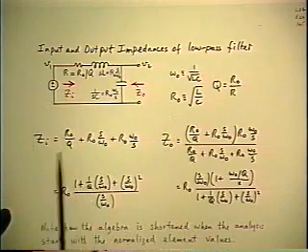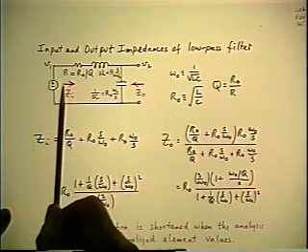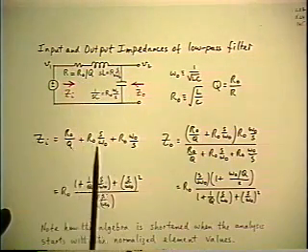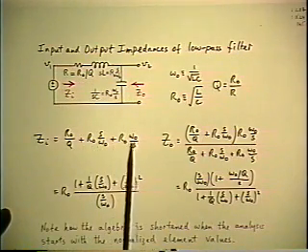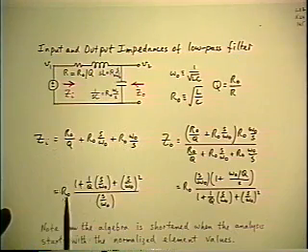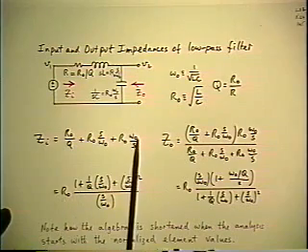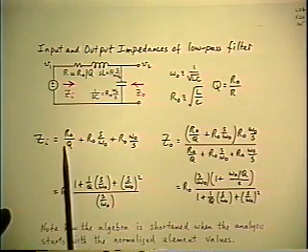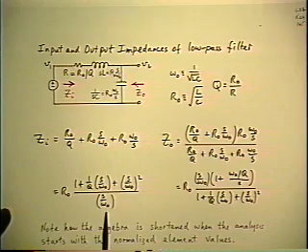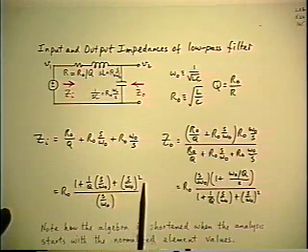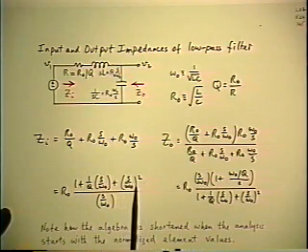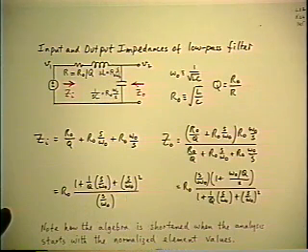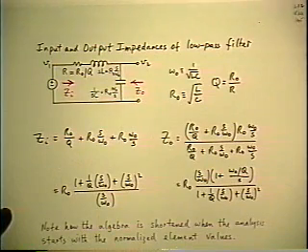So that now, in the very first line, when you write the input impedance, you simply write down the sum of those three reactances, and immediately you see that the R0 is a common factor. And in one more line, by bringing the omega 0 over s out front and putting it in the denominator, immediately you reconstitute the same quadratic that we had before in the voltage transfer function. This has been done now in 2 lines instead of 4. Simpler, shorter, and better.